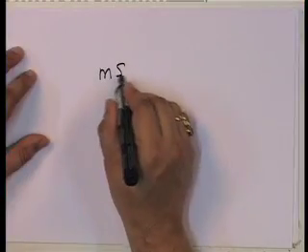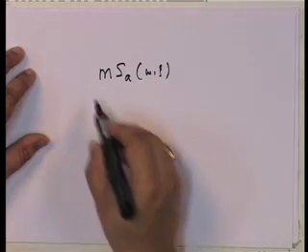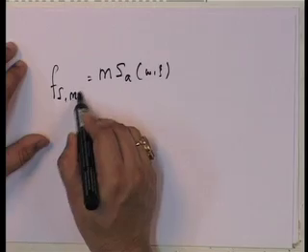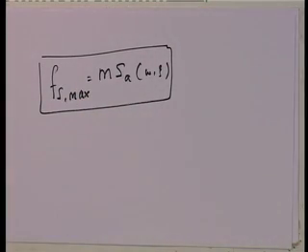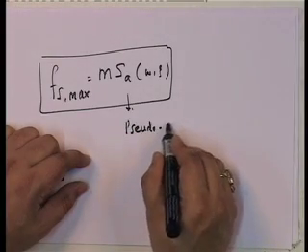It actually represents, if you look at this, this gives me the equivalent force that is applied to the structure due to the ground motion. So, in other words, I have made the ground motion, you see the earthquake ground motion has been transformed, through a specific form of the response spectrum into a mass into acceleration kind of. So, the load is due to mass into acceleration, and this of course, acceleration is a pseudo acceleration,